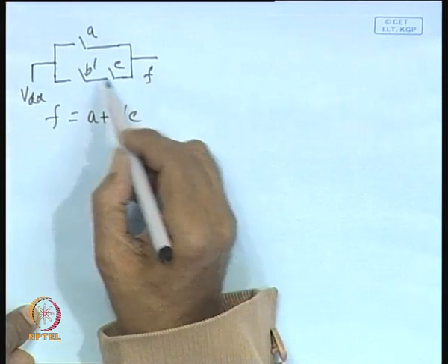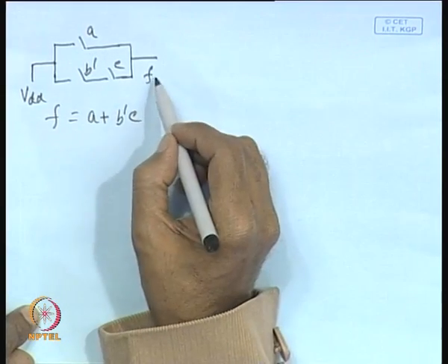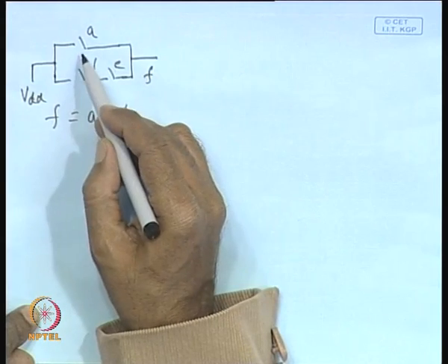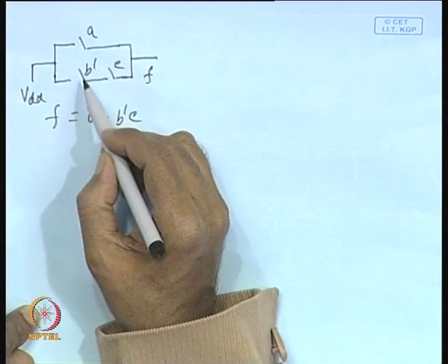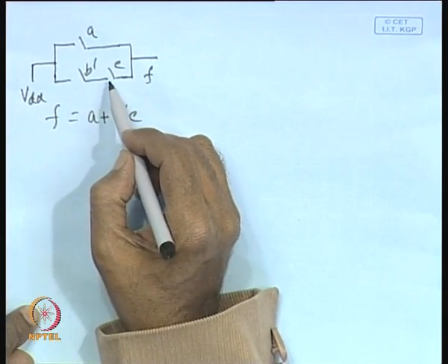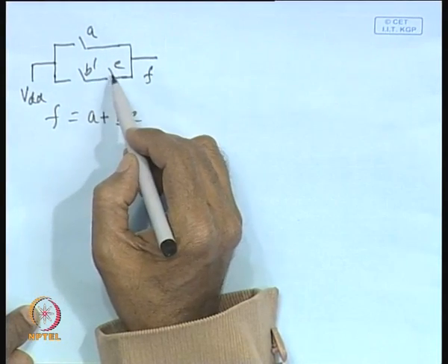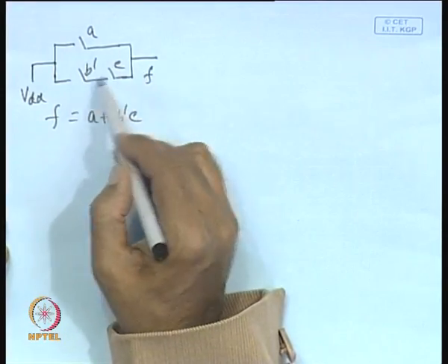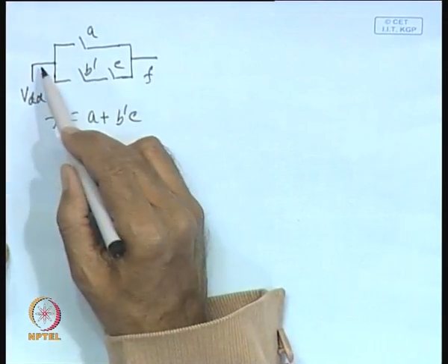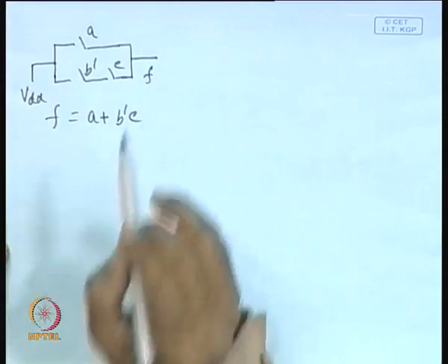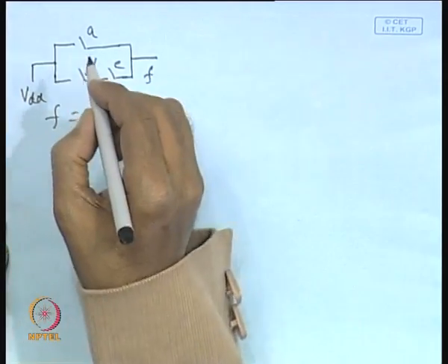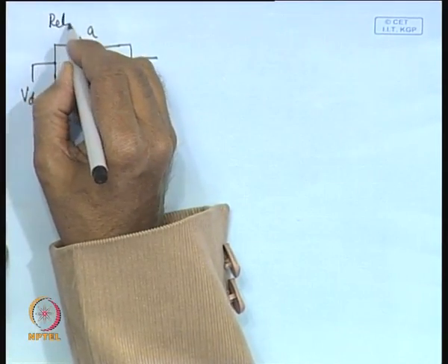So, as we can see, whenever the switches are off, we shall be getting 0 volt, either A is off, or B is off or C is off. In that case the path is off. That means, if there is no path, then output will be 0. So, this is how you can realize it by using relay logic.